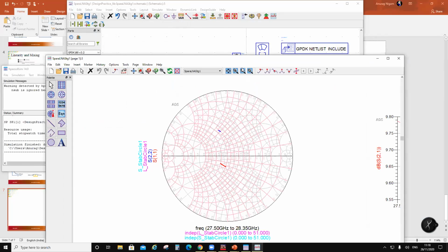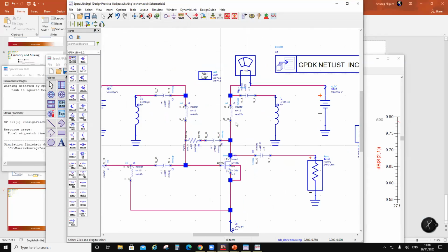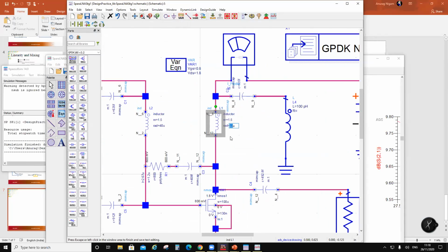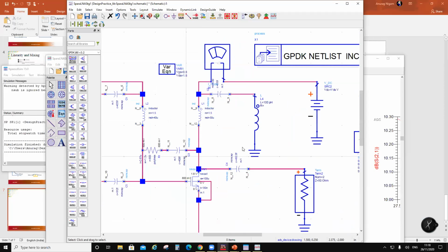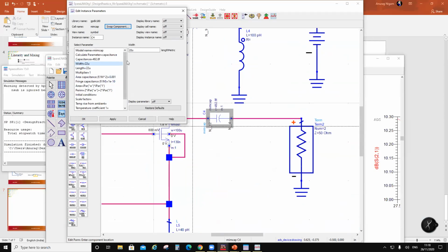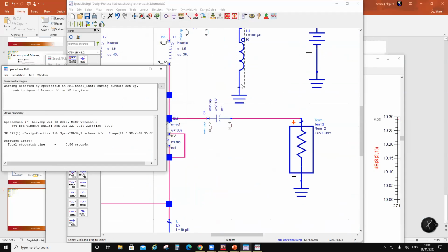Okay, and there is this part, and so I have reduced this a lot. So we started with what, 40, right? So let's put here 30. Okay, then reduce the inductance, the capacitance more. 40 and 40. So when you see the Smith chart, you should know which way the shunt and the series components are going to move you.